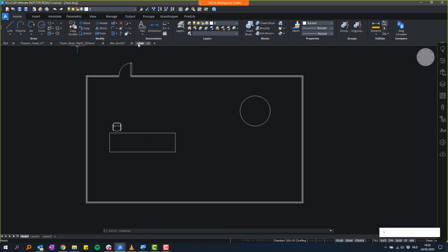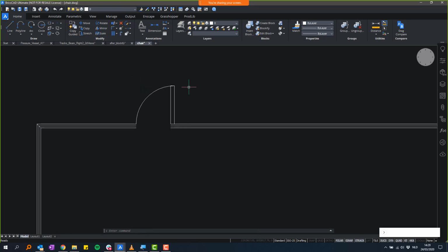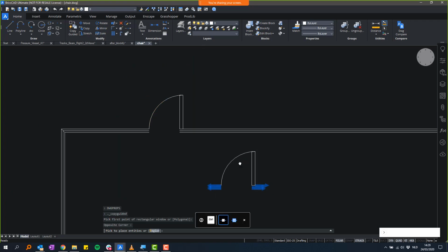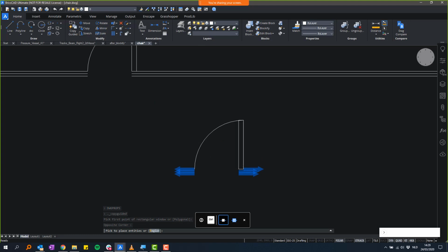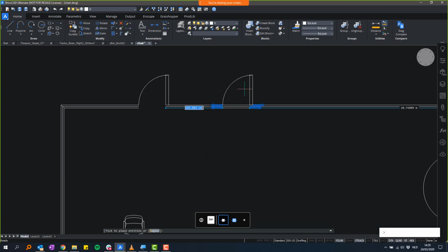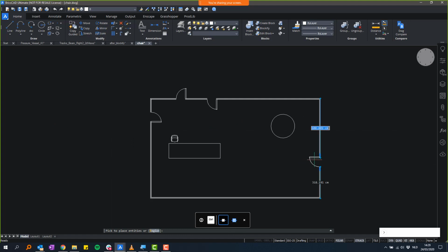Some other fun little tools that we developed are, for instance, copy guided, which allows us to copy objects along guide curves. So if I want to copy these few lines and polylines here, you see automatically it searches for these. What you see here, these blue arrows, are guide curves that it looks for, and automatically it will snap to objects that are similar. So it makes it very easy to copy objects along certain curves or lines. Okay, so these were some small examples of tools in 2D that we developed that we think can make a difference for users.